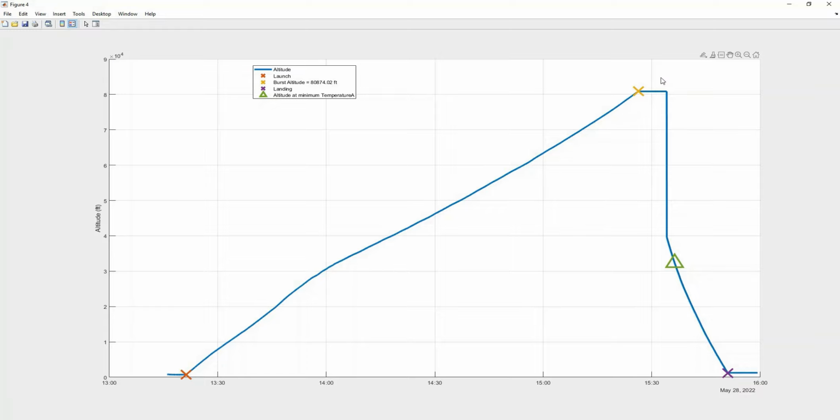Now, what's interesting is up here you can see that we've got a flat spot in the altitude profile. The reason this happened is because, I probably should have been a little bit more specific on the y-axis, this is GPS altitude. So what I believe happened is we were ascending, and then up here the balloon burst, and at that point it probably started tumbling, right? The payload box would have started tumbling, and I believe we lost the GPS lock here.